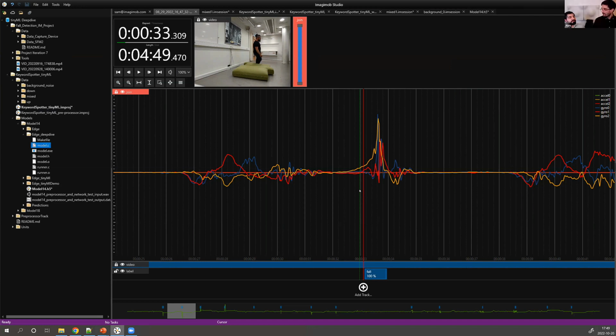Should I take it or do you want to? Yeah, I can take it. So with slow changing dynamics, what I would probably do is sample over a large period of time, and then you can condense the information. Usually with slow dynamics, you also don't need to react as fast. In some cases, we're looking at machine degradation over its lifetime, which could be like 10 years. Then you don't need to sample so often, and you can look at a large chunk of data and extract its characteristics, essentially.